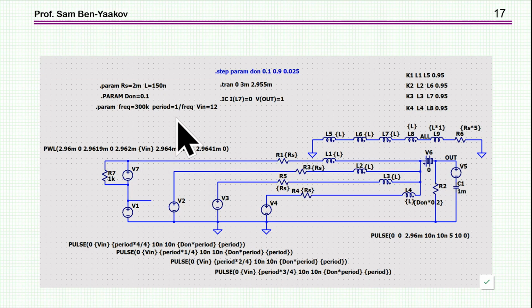So now I'm going to simulate this case. However, I'm not going to put in a control because it's going to be complicated to have a fast control, stability, etc. So instead, I'm going just to add a pulse to one of the phases. Okay, so these are running as usual, and then at one instant, this 2.96 millisecond, I'm going to add a pulse which is about 2 microseconds added to here, which is sort of mimicking the case in which you have a change and the control is sensing it, and then it is affecting the drive of this half bridge here.